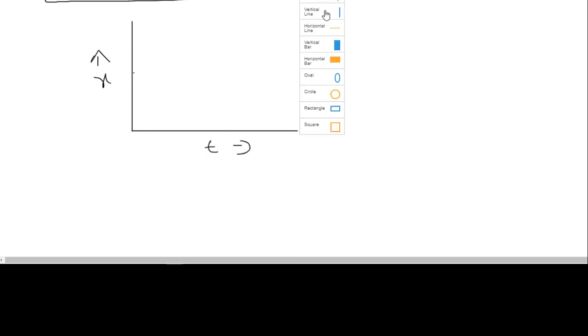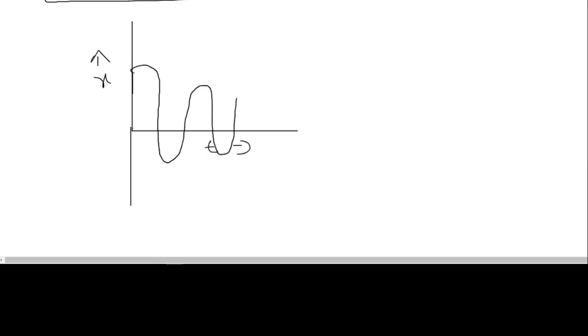So what will happen is, if you draw time with respect to displacement in under damping conditions, with a mean line here, and negative x, if the vibration is occurring, then it will start at a peak, then it will go on and it will not reduce gradually, whereas it should have been reducing gradually to 0. It will not reduce because the damping is not sufficient, so it will go on like that.